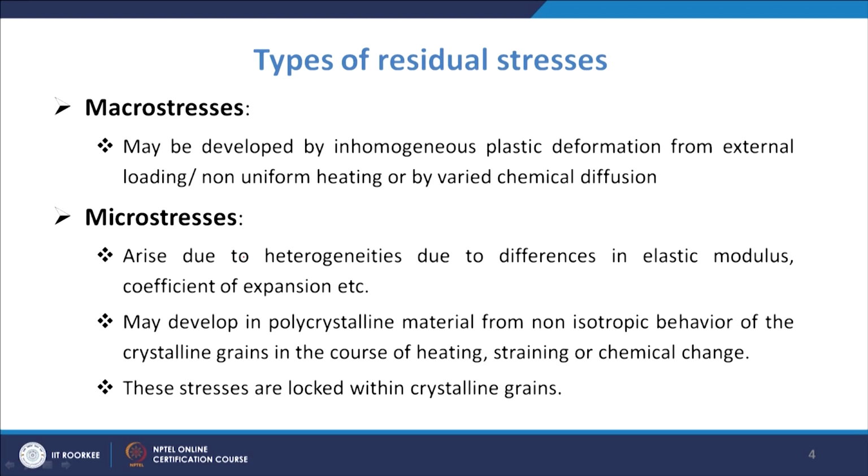Basically they are on a larger scale, which is why they are known as macro stresses, and that is why we look at a larger perspective, because of the inhomogeneous plastic deformation which occurs during welding. You have melting and then the plastic deformation also at that particular high temperature. That is because of the non-uniform heating and also because of the external loading.